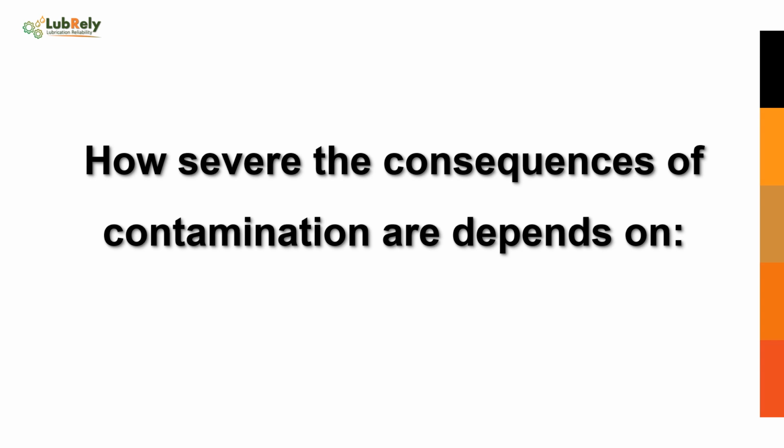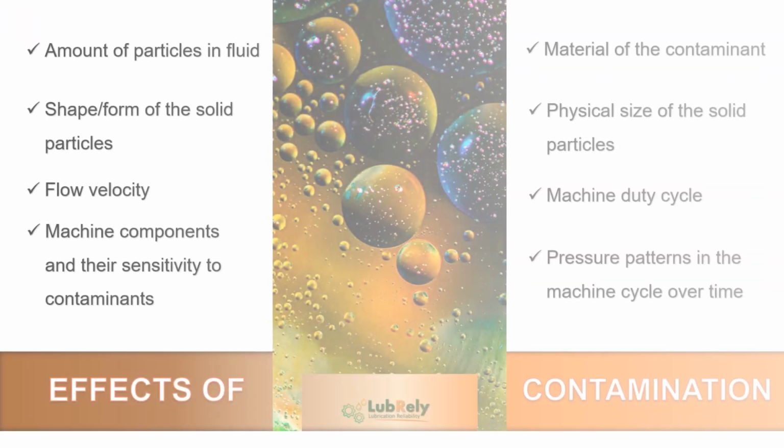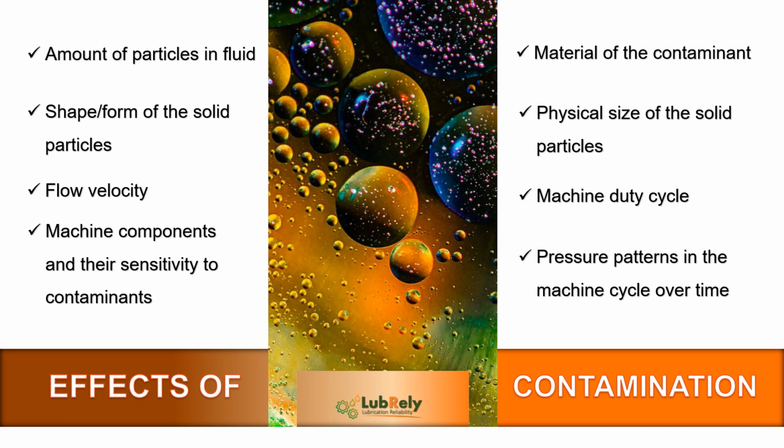How severe the consequences of the contamination are depends on the amount of particles in the fluid, the shape, form of the solid particles, the flow velocity, the machine components and their sensitivity to contaminants, the material of the contaminant, the physical size of the solid particles, the machine duty cycle, and the pressure patterns in the machine cycle over time.